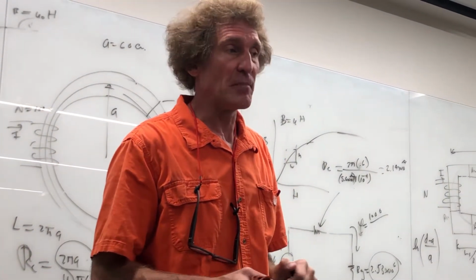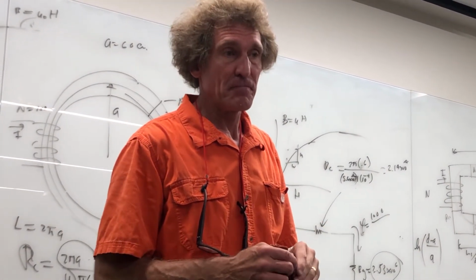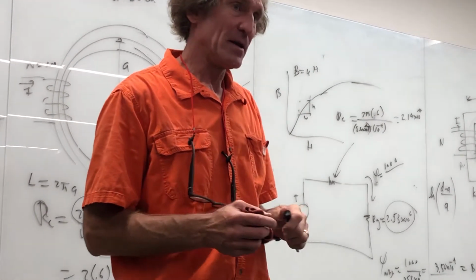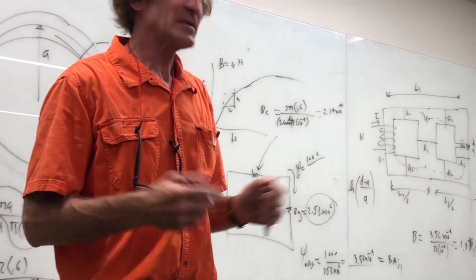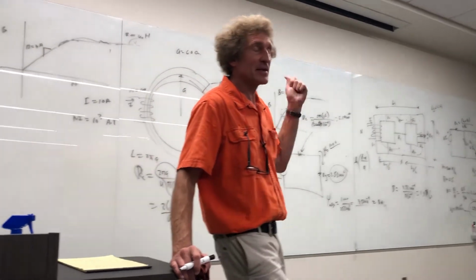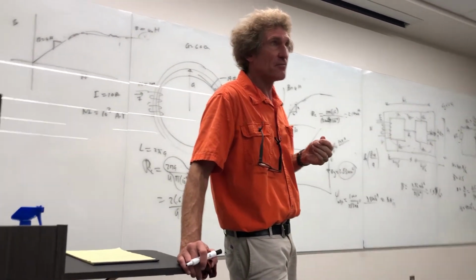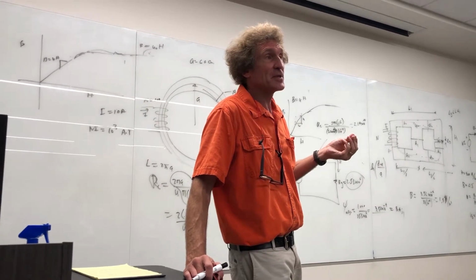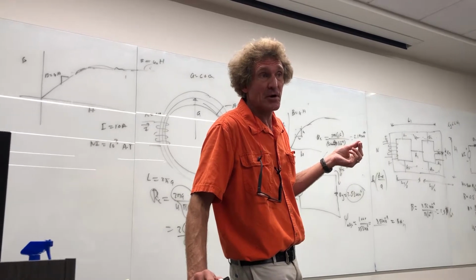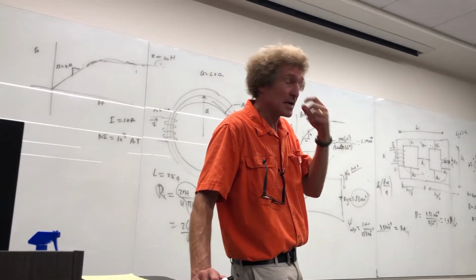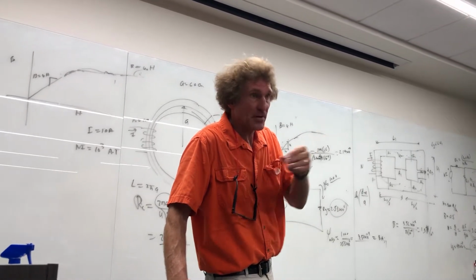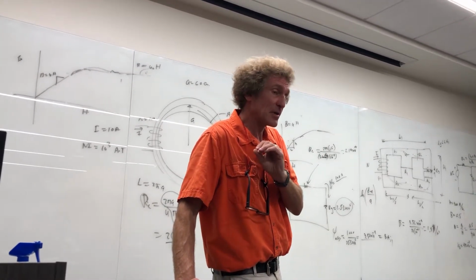It's a minimization problem. That's how he did it, didn't he? Duncan? I think so. The solution was not super clear. That's the way you do any nonlinear problem. You start by eliminating the effects of the core, in this case, and find the value of B. In our case it's unreasonably high, though it may be very low also. It may produce a B field in the linear range. Then you grab that value of mu and use it, and it's going to change the value of B a little bit. Then you refine mu and calculate again the reluctance and how it goes, okay?